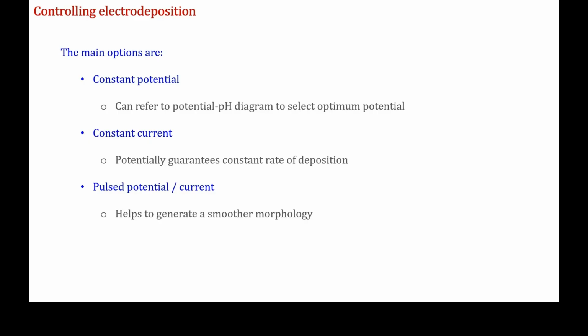But I think that what they do at the Royal Mint has the effect of constantly stirring the solution, which means you don't have the development of these big diffusion gradients, which start to affect the electrochemistry. So if you pulse it and you don't impose hydrodynamic control, you're essentially allowing the diffusion layer to recover rather than constantly growing with time. So doing it slowly and in a pulsed fashion can allow you to get a smoother deposit than you would otherwise have. So I think that's all I wanted to say.